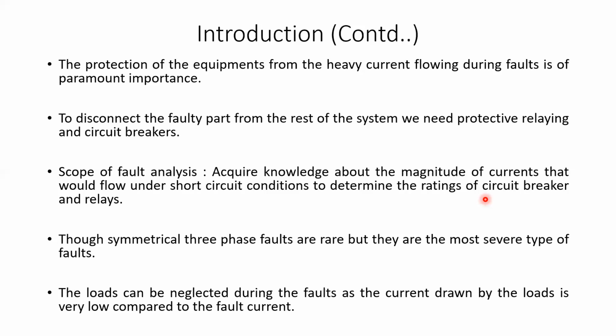The short circuit symmetrical faults, which involve all the three phases, are very rare, but they are the most severe types of fault. That means when a short circuit symmetrical fault occurs, the current that flows through the line is much higher compared to the unsymmetrical faults, which comprise single line to ground, double line to ground, or line to line faults.